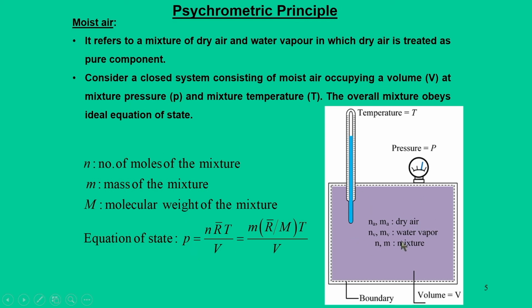So, one way to look at this problem is that when you talk about water vapors, water is treated as a pure substance. So, whenever we are in the saturated vapor region and beyond that, when you deal with a mixture, then we can use our steam table data to quantify the correct state or the magnitude of water vapor corresponding to that temperature.